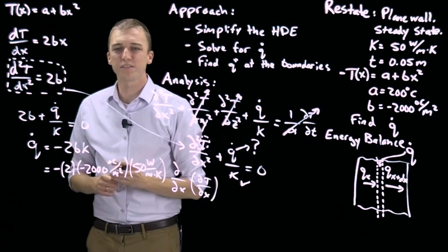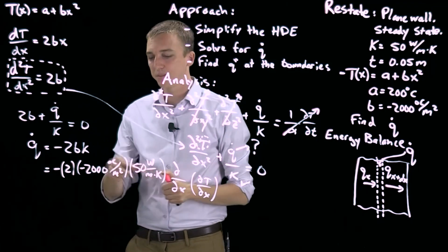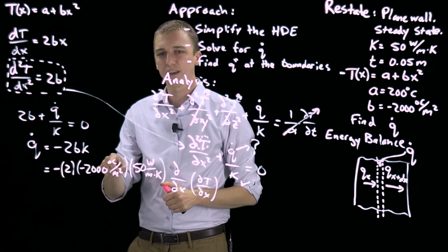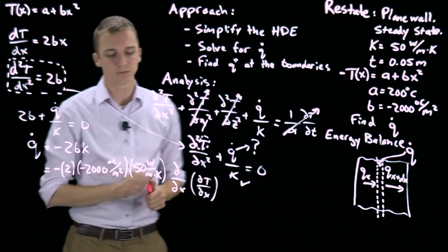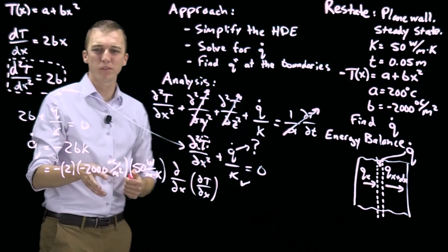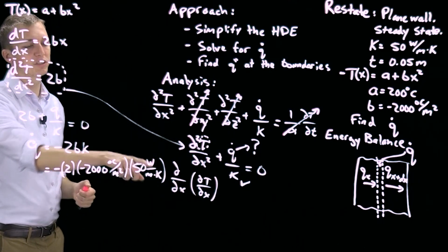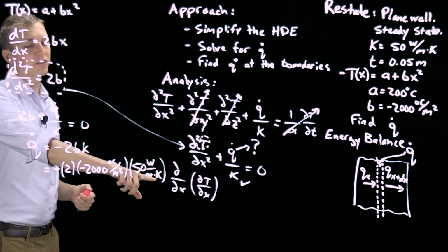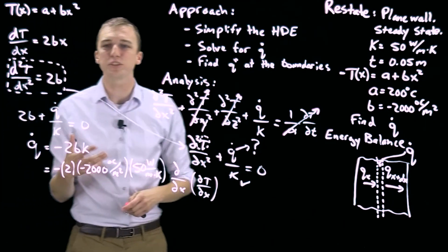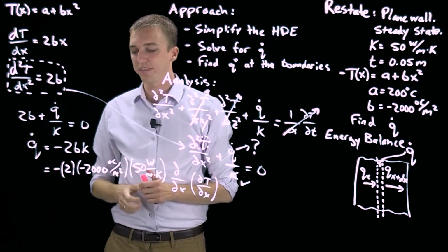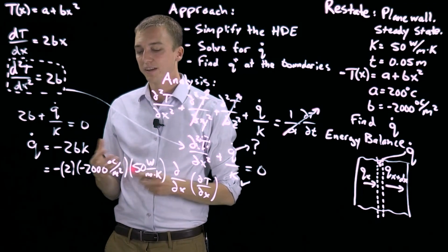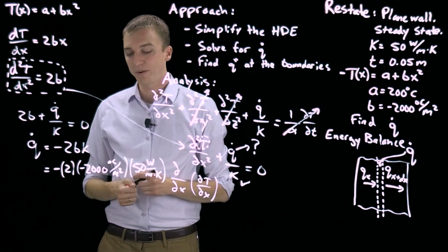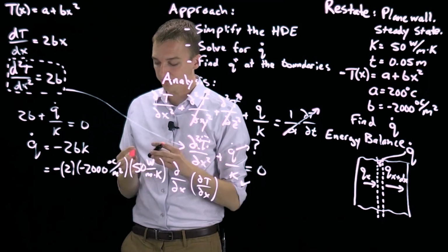Now there's been some confusion. How is it that we're able to cancel our temperature in Celsius with this, which is in Kelvin? But both of these represent a temperature difference. In this case, thermal conductivity, we had to take a temperature difference in order to find what that value was. Likewise here. Since it's a difference, then we can cancel Celsius and Kelvin.